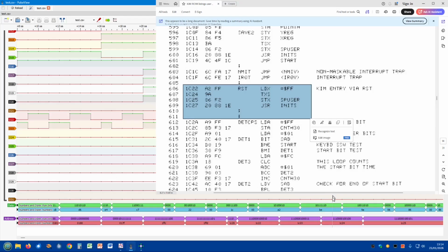I did do some testing to make sure bit 6 was reading correctly on the logic analyzer, and it's fine. The logic analyzer is reading that correctly. So bit 6 is not coming on, nor is bit 0 of the data bus. Just so happens back here, we didn't use those data bits, so it ran through okay. So now we've loaded BE into the X register instead of FF.